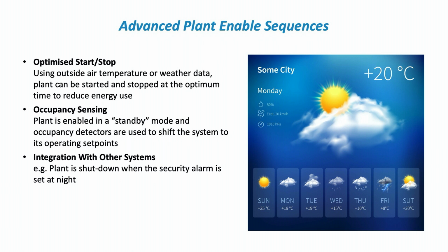We can also do a stop procedure as well. A building takes time to cool down. It's more unusual to use optimized stop because it can provide problems, particularly with the random working patterns that people have in modern buildings. But optimized start is implemented on a vast majority of buildings.